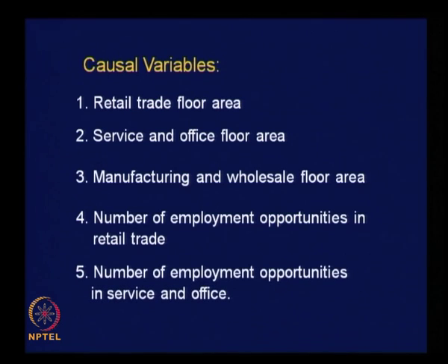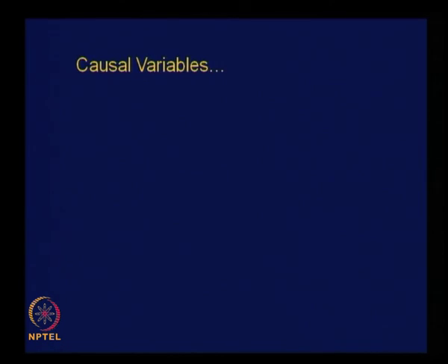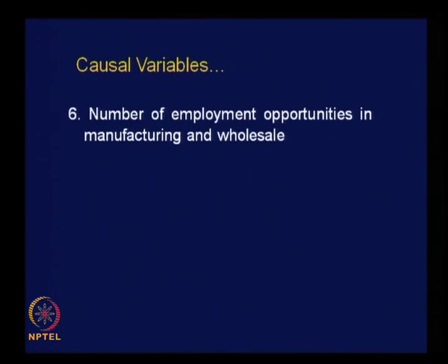If you get accurate data of this type, that can also be tried out as a factor influencing trip attraction. Number of employment opportunities in service and office, similar to the previous one. And number of employment opportunities in manufacturing and wholesale.